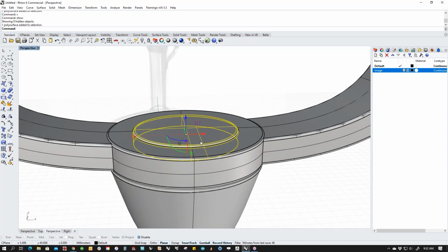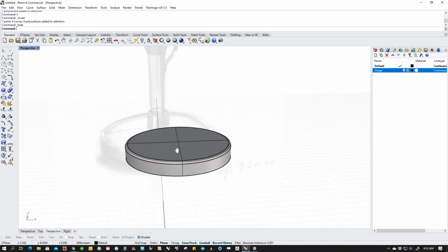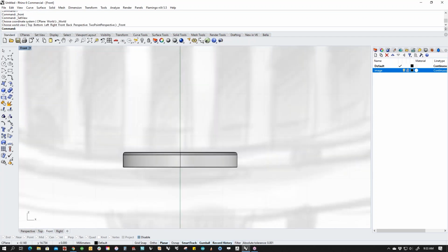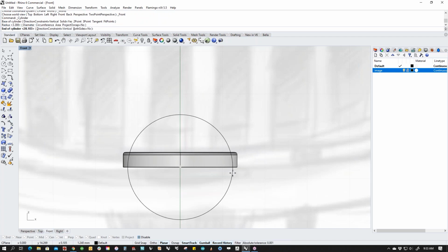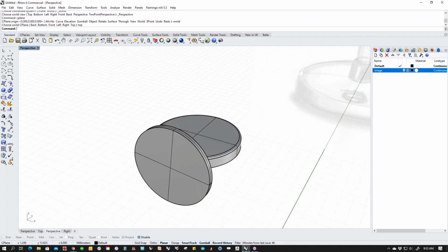So then we could probably assume that this would have either an Allen key or a flat screw slot through it or something like that. But let's go ahead and do that. So let's go to the right view, and I'm going to assume that it's got a flathead screwdriver slot in it, and it would be a pretty good radius. 0.15 thickness.